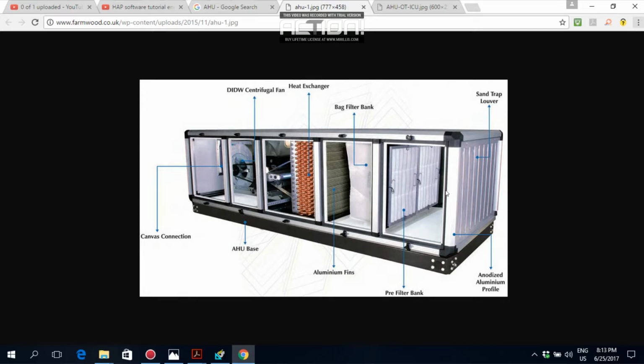Ventilation air provision means there will be a fresh air provision in the air handling unit. People who know exactly what I mean, the air handling unit or any unit, whether it is an air handling unit, package or DX unit, you will have a supply air duct, which is after this fan. Exactly before this blower there will be a return air duct, and there will be another duct which is outside air, and that is also called fresh air, and that's also called ventilation air.